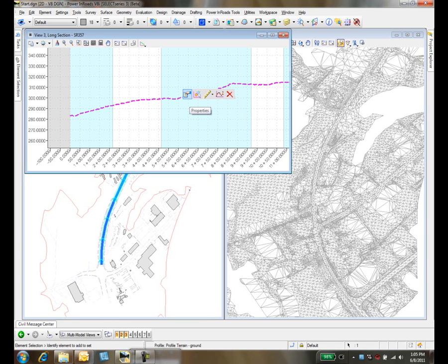So you're going to see a lot of consistency between all the different options, whether you're selecting a train model, whether you're selecting a horizontal alignment, whether you're selecting a profile, existing, proposed, or even the model itself. You're going to have these context toolbars. So these context toolbars know what I selected. So for example, it says, do you want to set this as your active profile?